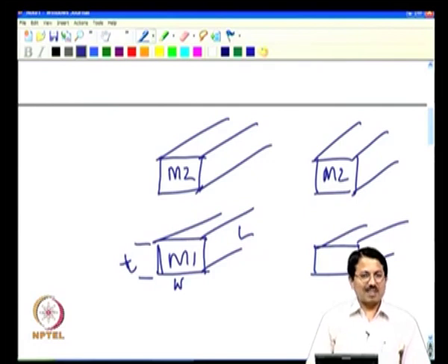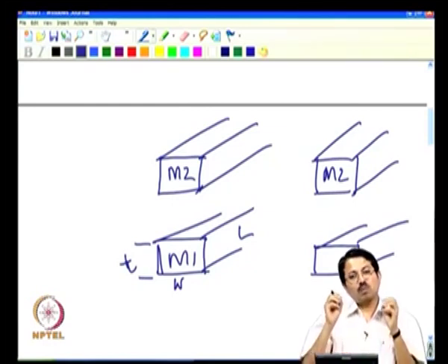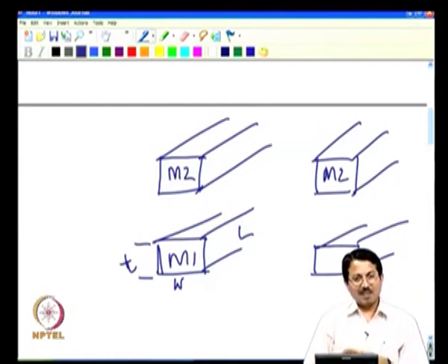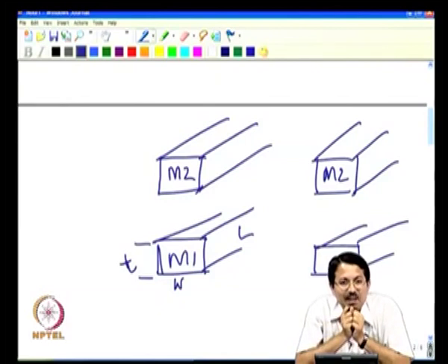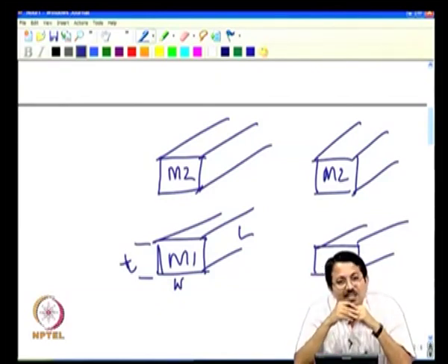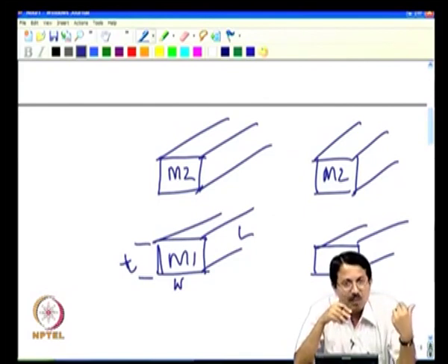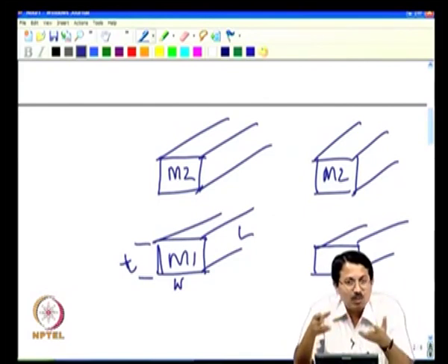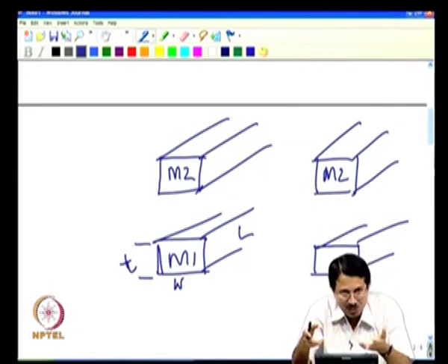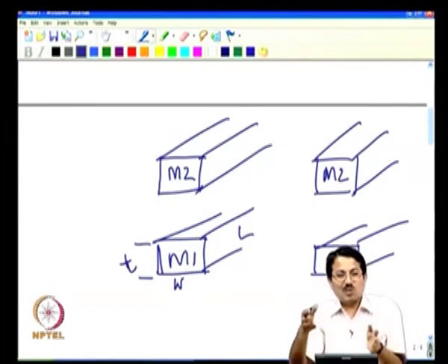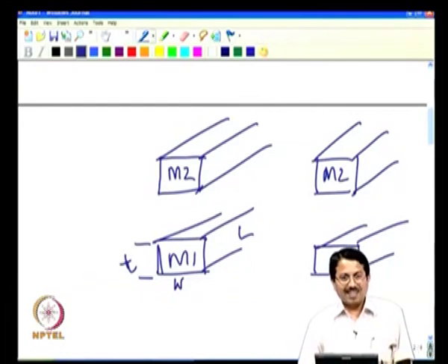That is why we said 0.7x, so that the chip area comes down, transistor area comes down and all that. But what has happened over the years is that with scaling we also put in more transistors in a new technology. We are not just happy with the performance gain that comes just because of the mere scaling. We want to increase the number of transistors very significantly compared to what it was earlier, okay. So if previously you had a million transistors, you want to put 4 million transistors in a new chip, in a new technology, and hence you continue to use the same area or even bigger area, okay.